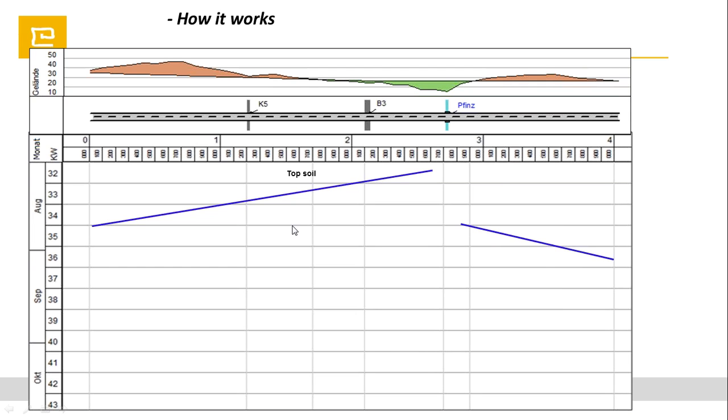And of course, TILOS has special calculations, such as crew movement links, which means we can estimate dates at 50 meters per hour driving for our machines from this point to this point, and how long it will take. And also we understand from here which areas we couldn't plan and there is no plan for.